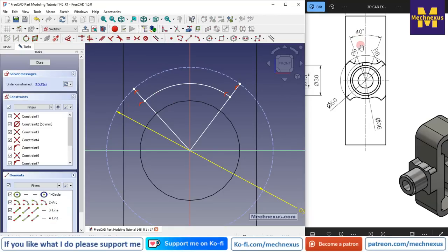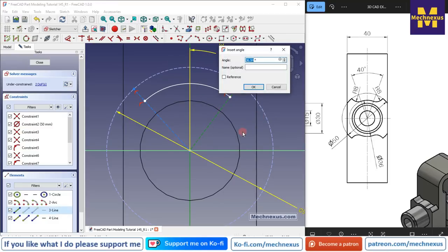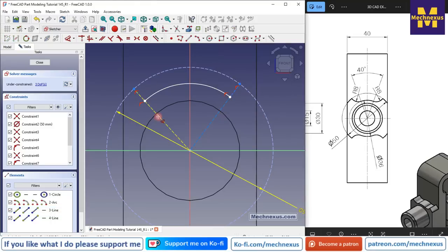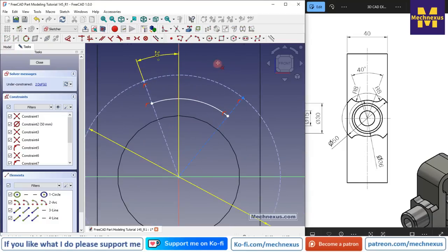Now here the angle given is 40 degree, so this will be our construction line, and we will select a smart dimension, select this and this, and here we will provide the 20 degree. Let's give the first dimension on the left hand side and give it a 20. And now we will make this angle dependent on this.